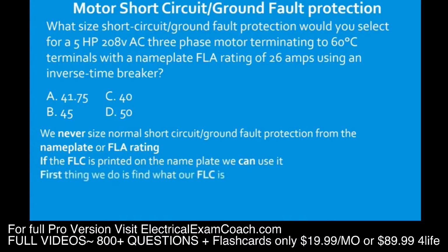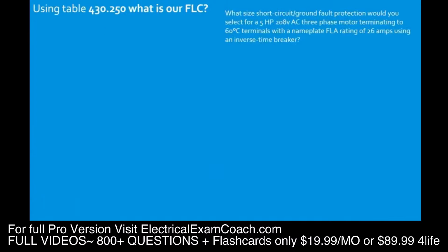But what we're going to do is like we normally do to find our FLC, and we're going to head to our FLC tables. So let's flip to our FLC tab. Using table 430.250 because it's a three-phase motor, what is our FLC? We start on the left-hand side for our horsepower, then we come off and tee with our voltage, and we're going to select our FLC. In this case, it's 16.7 amps. Now we have to go check out a new table, okay?